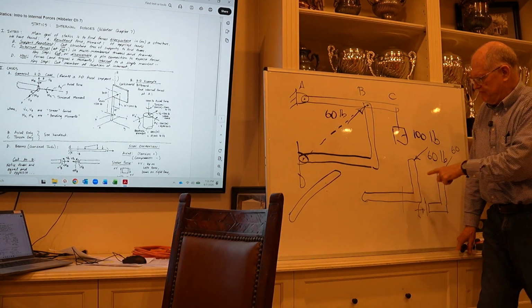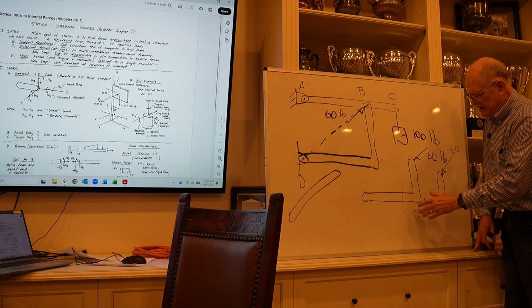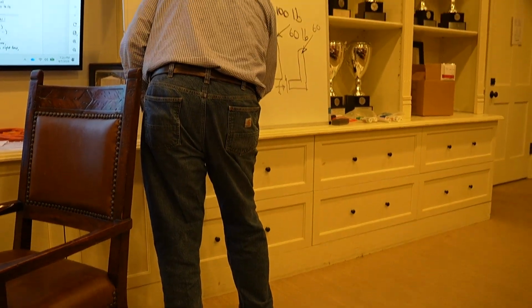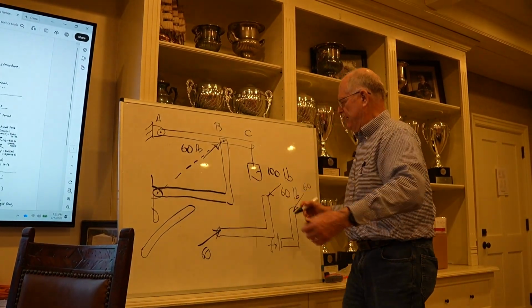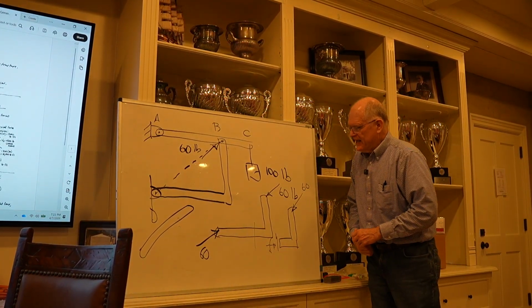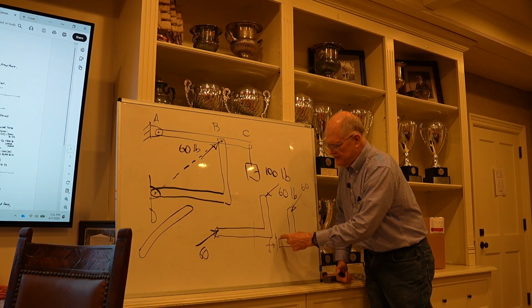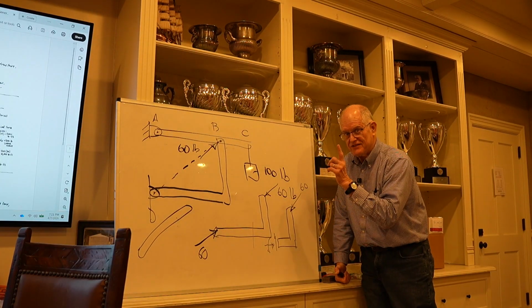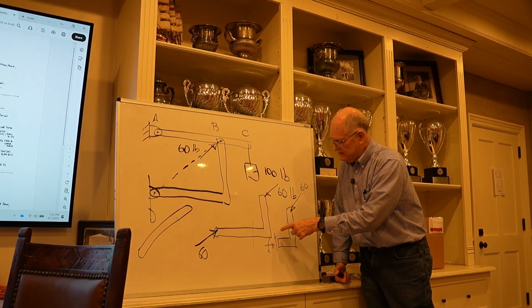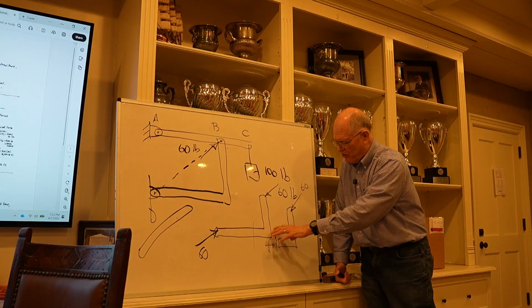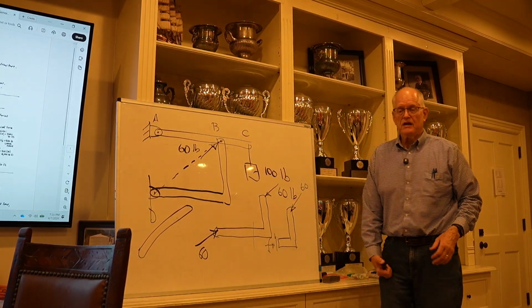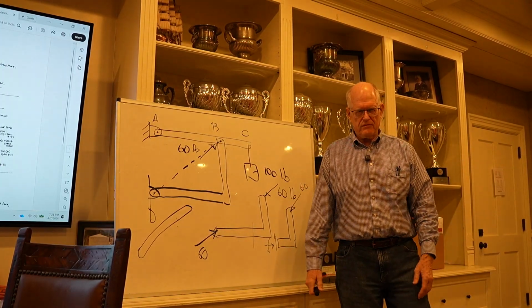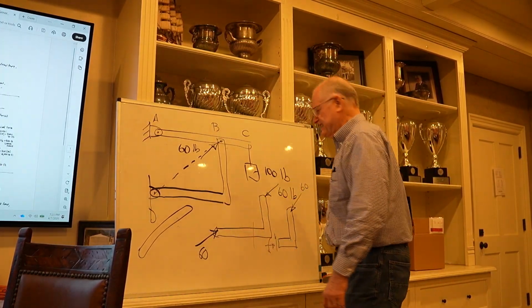So if we take this L-shaped member here and cut him here, he's in static equilibrium, which he will be, so whatever, this is 60 and this is 60. So the whole thing is in static equilibrium. But if we cut him here, these internal forces have to be such that this section of this guy is in static equilibrium. So these guys are equal and opposite of him and have the appropriate bending moment to keep this guy in static equilibrium. So every piece of every member has to be in static equilibrium. Okay? So that's what we're doing with the internal forces. Does that make sense?